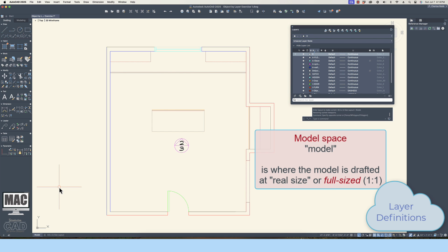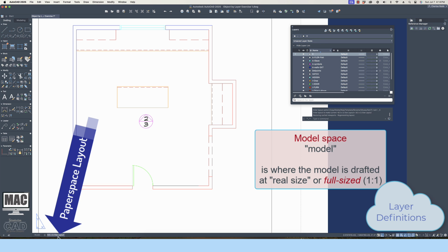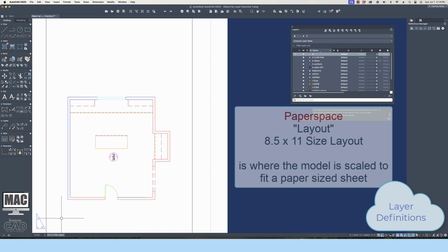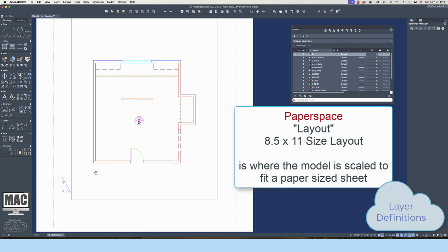Now that we've completed the drafting portion of this assignment, it is time to save the drawing and create a virtual print from the Paper Space tab. Remember, the drafting of objects always occurs at full scale or 1:1 in model space as defined by this tab. The full-sized objects must be scaled to a smaller size in order to fit on a paper that can be printed. The scale must be one of the accepted scales from the architectural scale list.